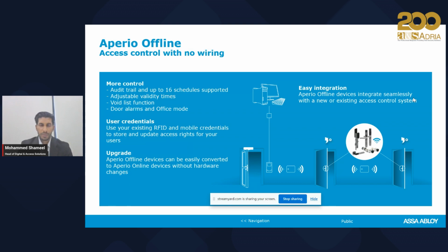Here, you are essentially getting a delayed online system rather than a completely offline system. The reason being, once the card is used on these offline locks, the same card can later be used on an online wired card reader, which sends back all the transaction details previously loaded onto the card to the access control software, and any new access permission changes in the software can also be written to the access card as well.